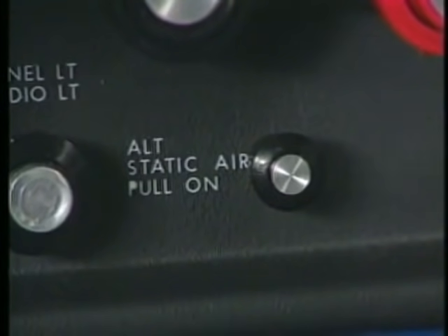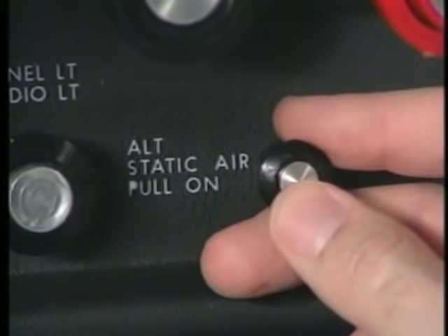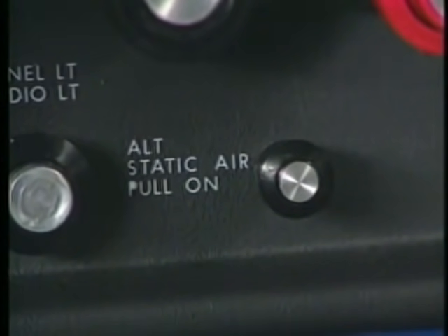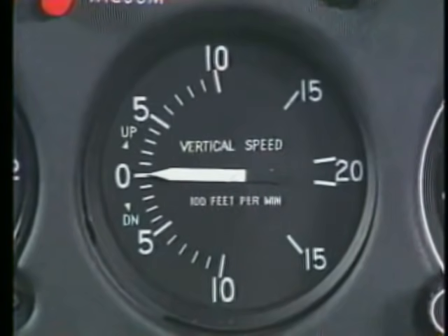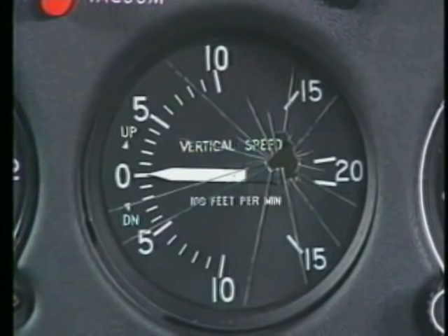Many aircraft have an alternate static source. On a non-pressurized airplane, it is usually vented to the cabin area. If an alternate source is not available, you could, as a last resort, break the glass on the VSI. With the glass broken, you should consider any VSI readings unreliable. In both cases, the pressure inside the cabin is slightly lower than that surrounding the airplane. Therefore, the altimeter will read higher and the airspeed faster than normal.